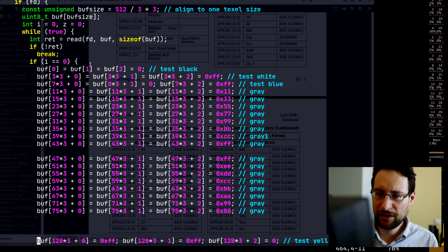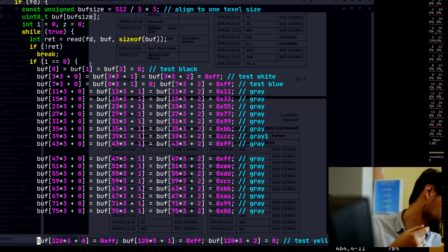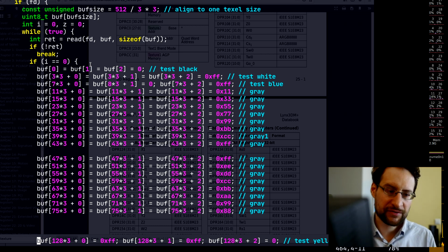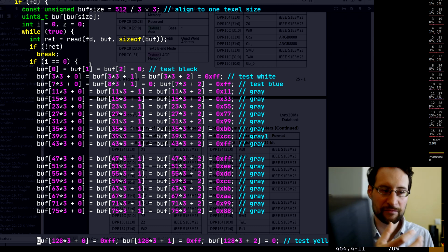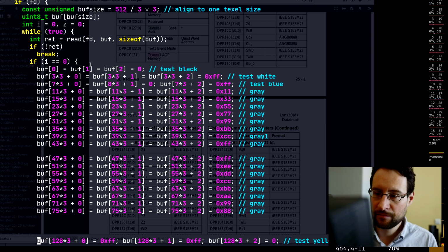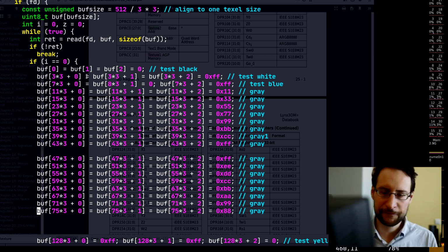Initially we load the texture, similar to the Verge and Voodoo. Usually we do this on DOS, but because this machine doesn't network boot it and DOS is not the easiest, we exceptionally run this in Linux, but this doesn't really matter. We map some registers and bitbang the registers from user space like you would do in a microkernel. And as you see, I added more and more test patterns to understand how this tiling stuff works.